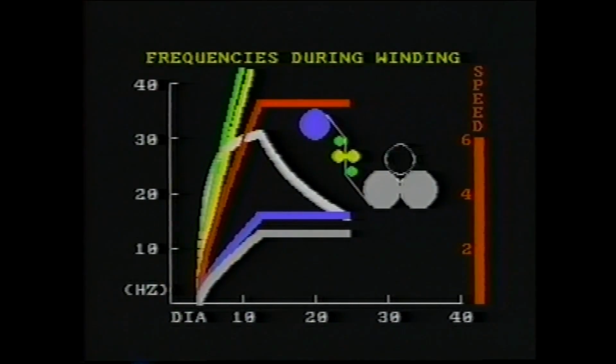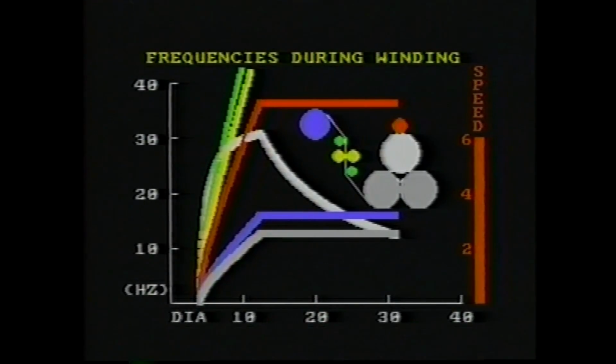As seen from this graph, the rewound and unwind paper rolls can produce large driving frequencies up to 40 Hz, and the smaller diameter slitter rolls can generate forcing functions at frequencies up to 80 Hz for an 8,500 feet per minute winder. Additionally, roll beating between rolls rotating in dynamic vicinity of each other can generate sum and difference beat frequencies. If any of these rolls rotates at a frequency nearly equal to one of the many system resonances, vibration amplitudes can suddenly increase by almost an order of magnitude.